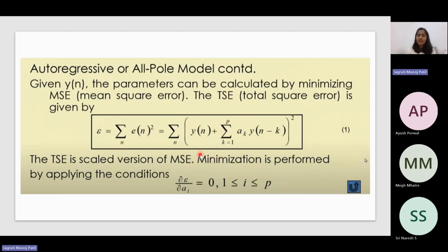That is essentially the same thing, but here keep in mind that you should not get stuck in a local minimum. If you get stuck in a local minimum with any such method, say a gradient descent method, where you are differentiating again and again, you will never reach the global minimum. So you need to ensure that the derivative of the total square error with respect to your autoregressive coefficient is 0.